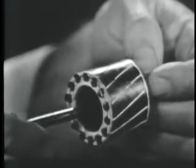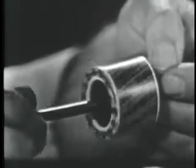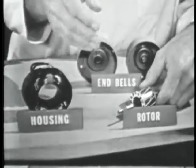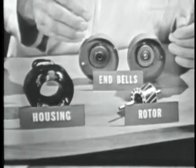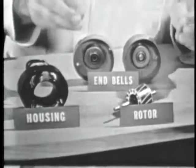Not at all. Now, this particular rotor design is called the squirrel cage rotor because it resembles the exercise cages used for pet squirrels. Like the squirrel cage, the rotor is very simple to construct. Simplicity of construction, which of course leads to lower cost of manufacture, and a very rugged design, makes the induction motor a very popular one. There are no wires on the rotor to burn out, no brushes to wear, no commutator to get scratched or pitted. All in all, a pretty good motor. Of course, it's not perfect for every application. It does have certain limitations, but even so, it's used quite extensively.